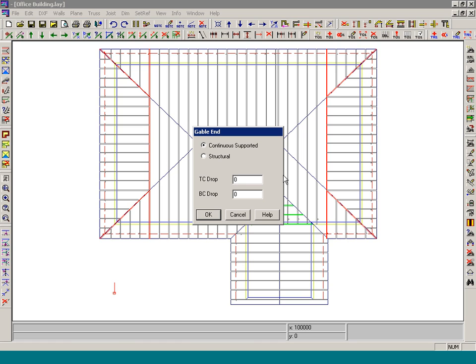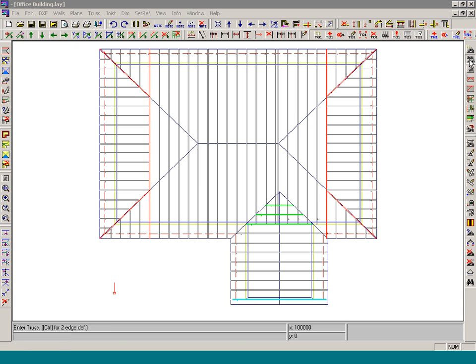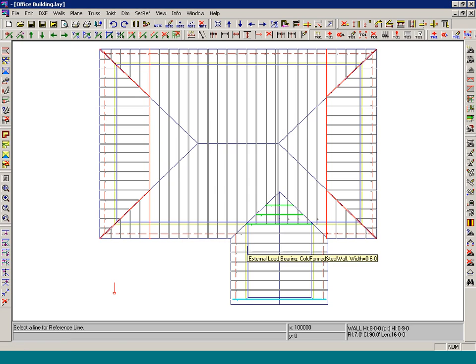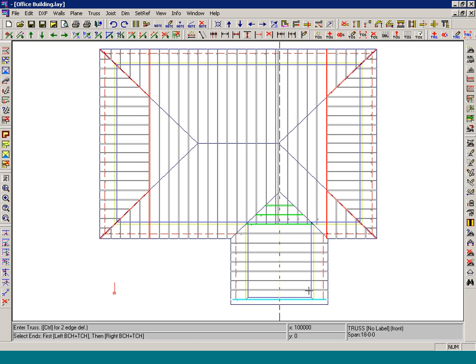Here, the designer changes the outside truss to a gable-style truss, drops the top down to allow room for rafters to cross the gable, and extend to the eave line. The rafters are input as normal trusses, and then changed to rafters.